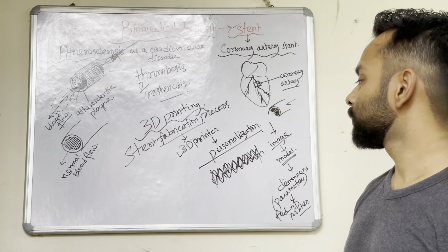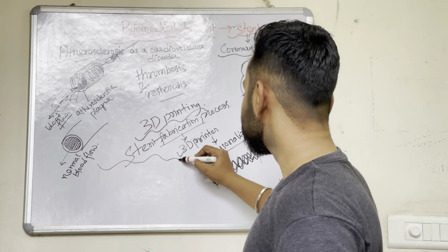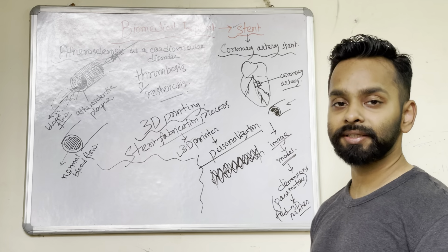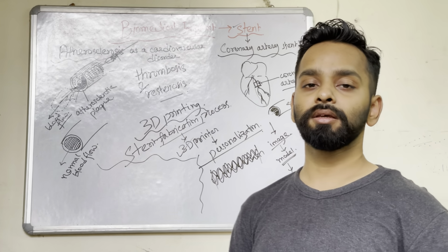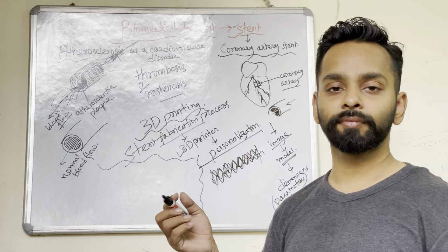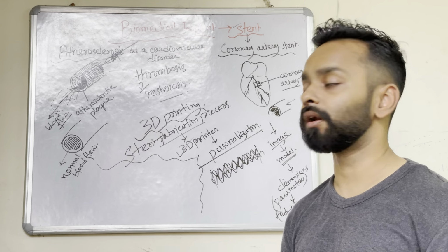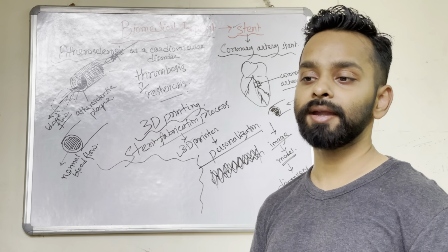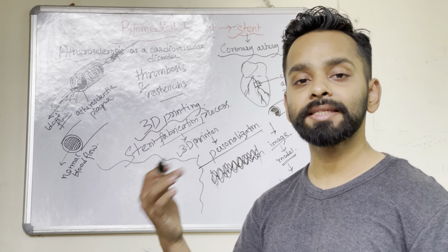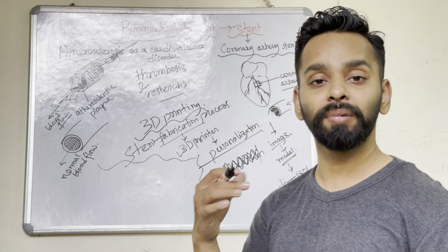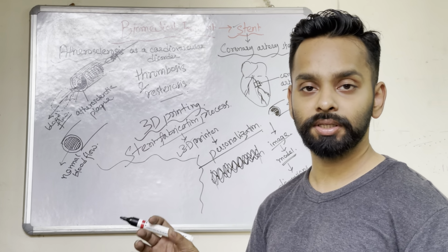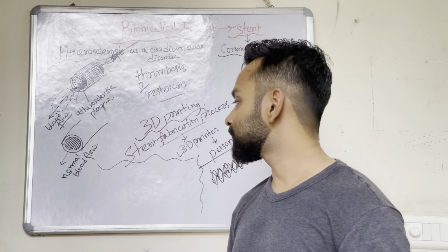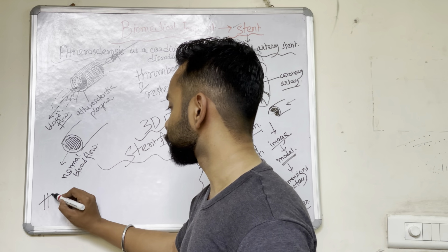Now, different new modifications have been made to this stent fabrication technique, wherein these stents can be loaded with different types of drugs. Such stents, which are loaded with drugs and which will then release the drugs in the body, in the bloodstream, in that particular cross section of the artery where the stent has been placed, are known as drug eluting stents.